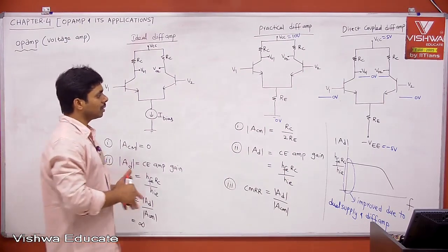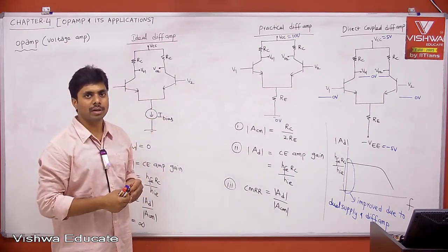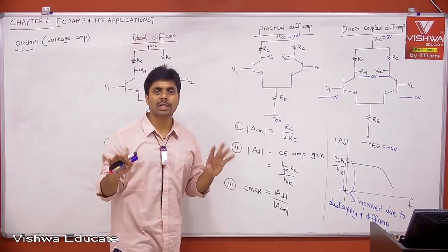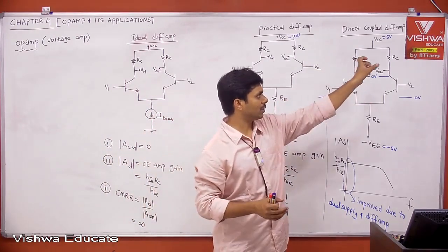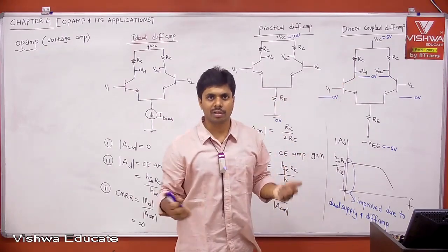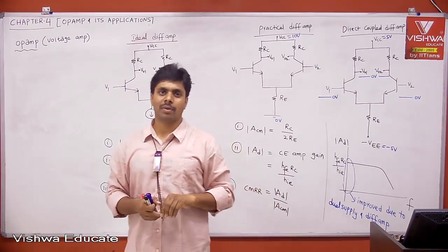Therefore we got it. Now can I say the definition of op amp: direct coupled, yes, direct coupled, we don't need any capacitor. High gain, if you take the output of this and give it to one more stage, you will get very high gain. Differential amplifier, this is a differential amplifier. The first stage of an op amp is a differential amplifier.